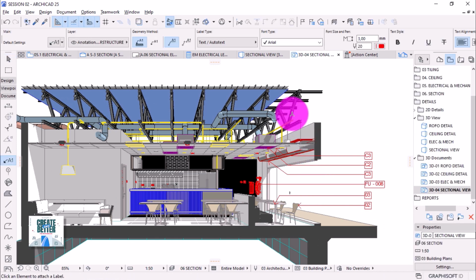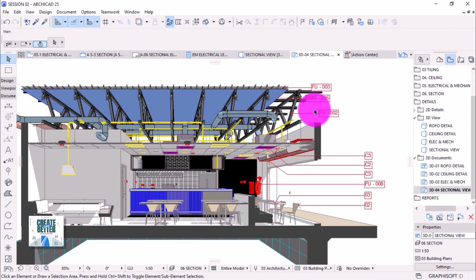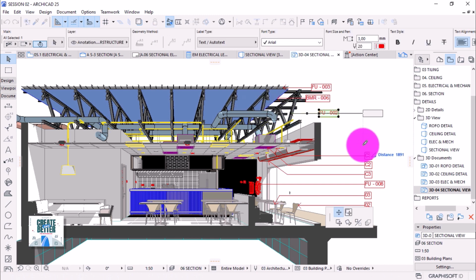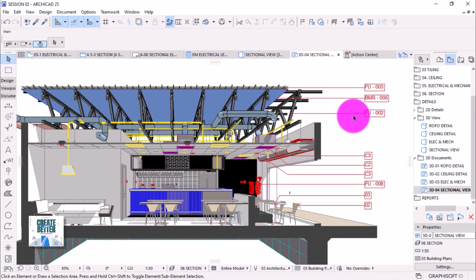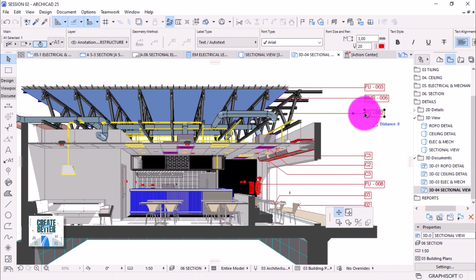Then pick the parameters of a straight one and do the trusses and the pair lines together with the roof finish and the roof insulator. Perfect. Now it's time for me to align them to the others. Yep.